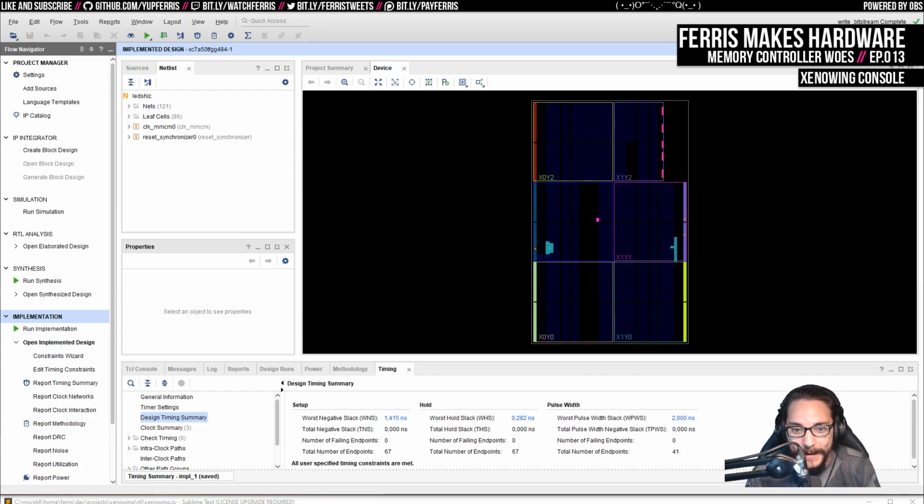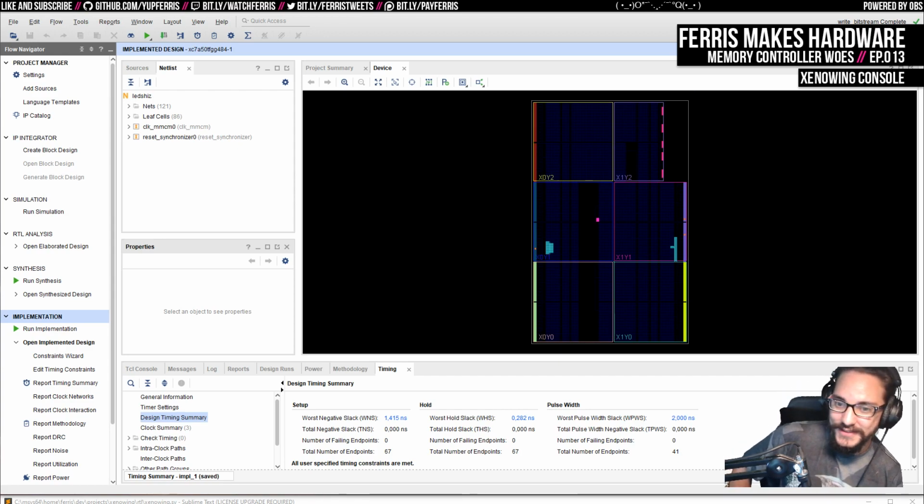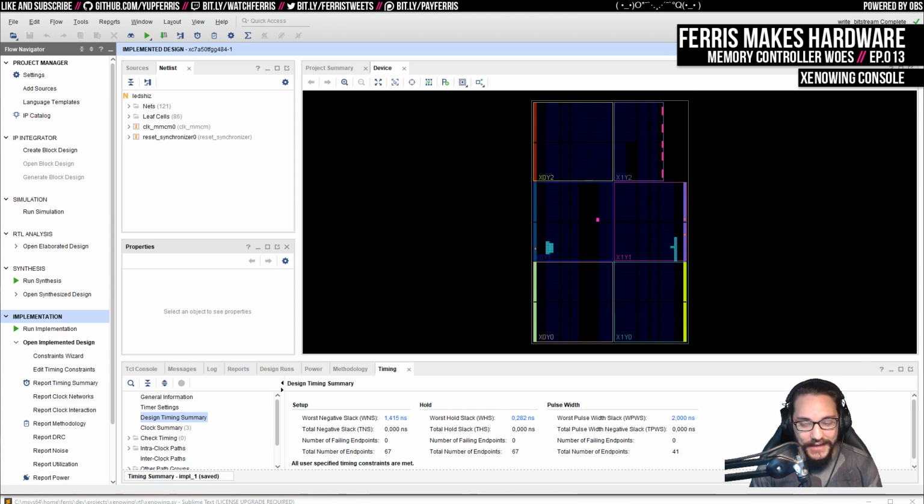I'm not really sure. I did look into this feature called design partitioning. I think it's actually called blocks in Quartus. And the problem there is that that's not available in the free version of Quartus, so I can't even explore actually partitioning the design like that. There might be some floor planning stuff that I could explore, but it just didn't seem like that was the kind of issue that I wanted to work with, at least not yet. So I'd rather just clock my design down and then, for example, maybe use a FIFO between that and the memory controller, and then just have the memory controller work as is.